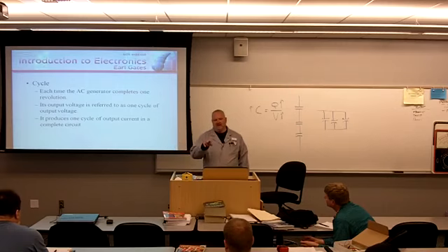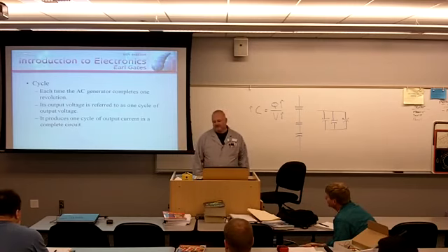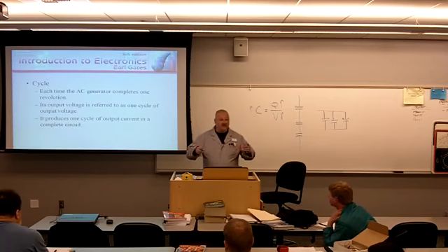Because if you don't have anything connected up to that and that thing's just rotating through, will the electrons have anywhere to move to? No. So if they don't have anywhere to move to, you don't have current. So it's just going to sit there stationary. You have to complete it to a circuit. But even if you connect it to your meter, is your meter a load? So if you connect your meter, you just completed the circuit, now you're going to measure. Now the electrons have a place to shake back and forth to. You've completed the circuit.